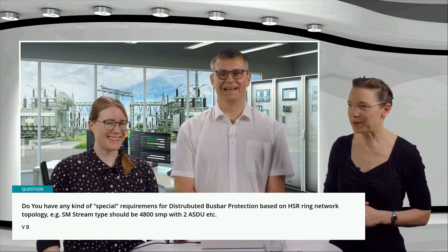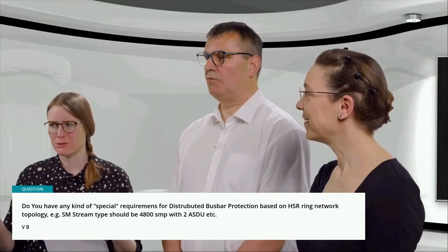Do you have any special requirements for the distributed busbar protection based on an HSR ring network topology? For example, the SMV stream type should be 4800 SMP with 2 ASDUs. Do you want to answer? I can say that for the 7SS85CU solution, the stream type is fixed on 4000 Hertz 1 ASDU. But honestly, for the IEC 61850 compliant solution, both is possible, I would say.